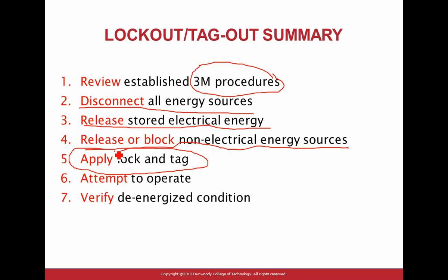So you go to your disconnect, and you're going to lock it with your lock right here. I don't have a lock here. And you tag it with your name, a tag and a lock, and one of these. Now nobody other than you can lock and tag. And by the way, it's against the law for somebody to go cut your lock.